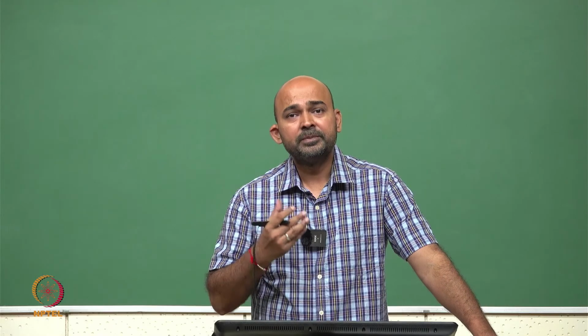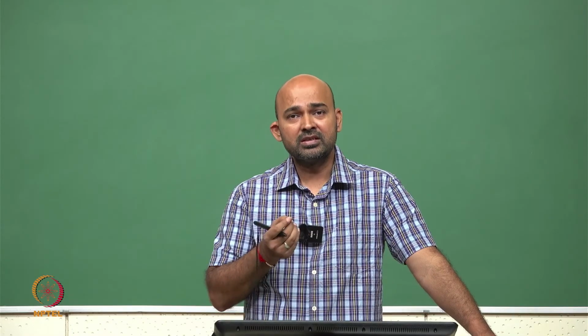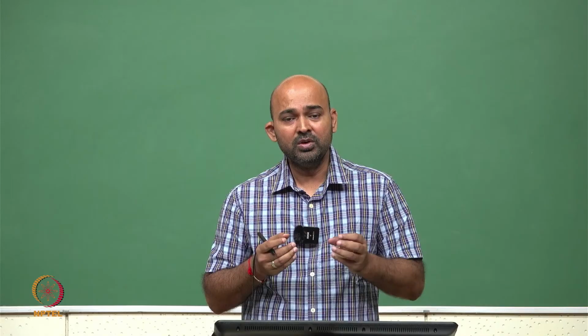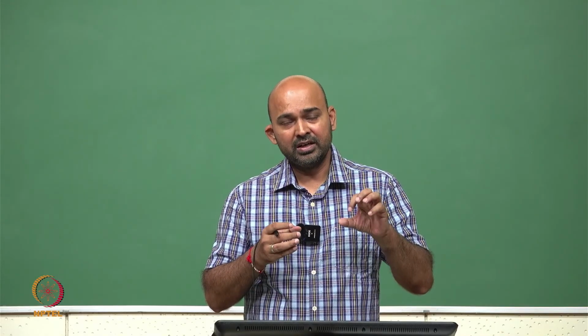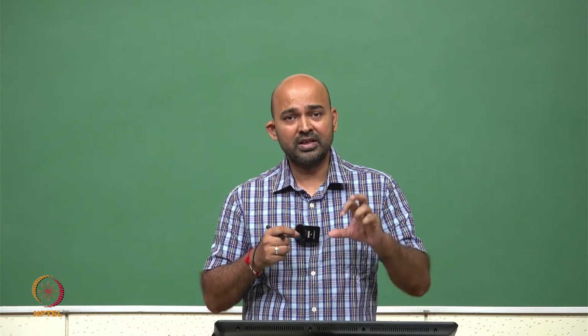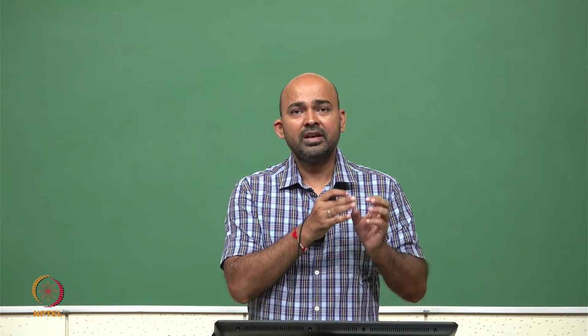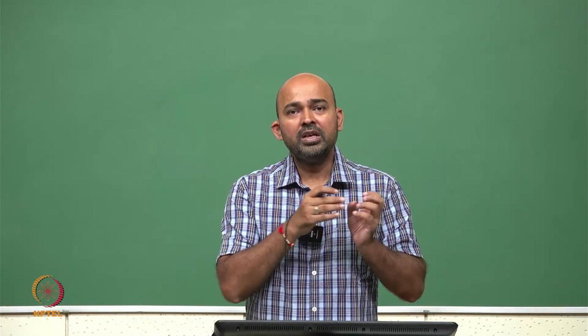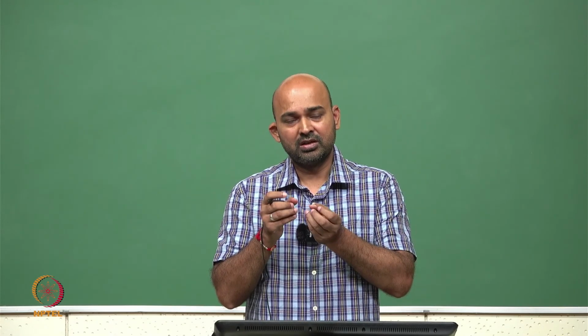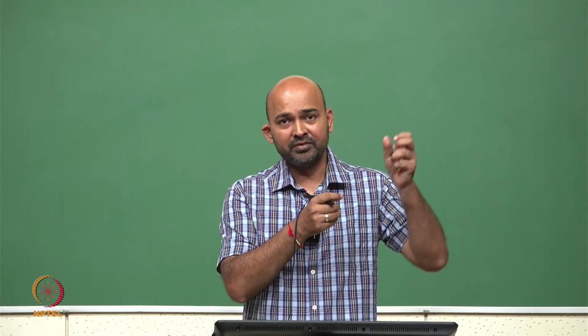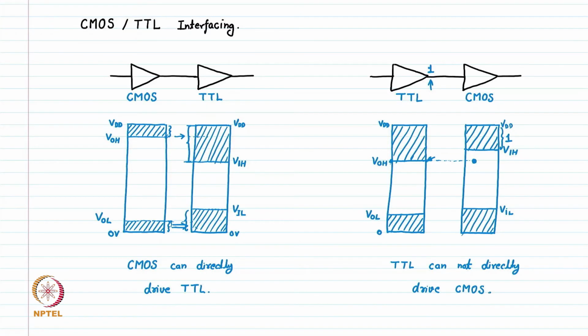One solution is, because this resistive drop will always be there no matter what we do, because of the current flowing in the resistance, this IR drop will always be there. So, this resistance itself will not be able to pull this output node to a very high value VOH, because there is a BJT there which is drawing this current through this resistor.